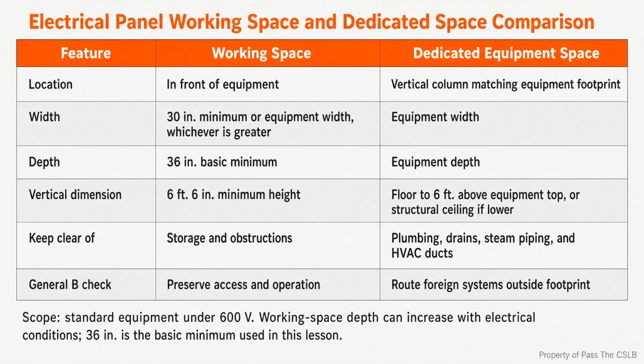This is where accessible and readily accessible can be confused. A breaker that can be reached only by bringing over a stepladder is not made acceptable merely because a ladder exists on the project. For the field check covered here, I remember the maximum handle height and verify it from the finished floor or working platform.